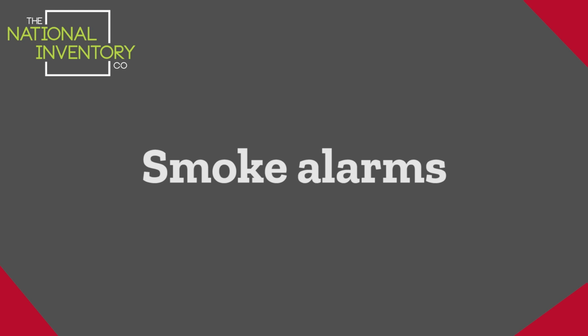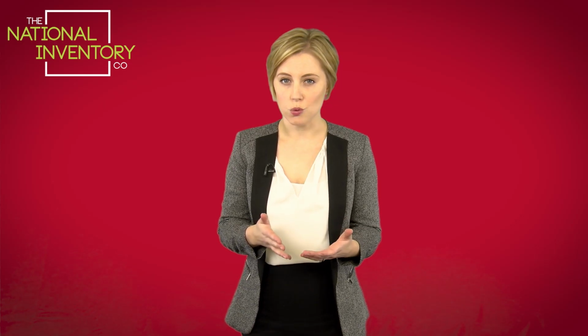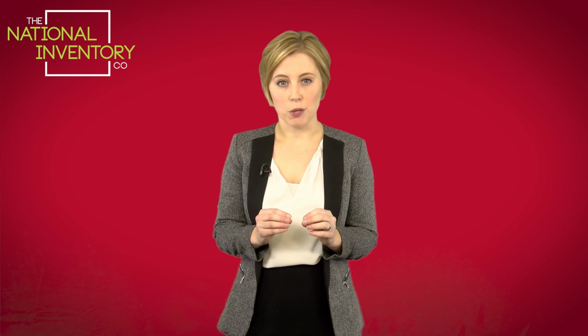Smoke alarms. There are a variety of smoke alarms on the market, mainly hardwired or battery operated. Hardwired smoke alarms are connected to the mains, but they also have a battery backup inside. In case the mains electricity fails, then the battery will kick in, allowing the smoke alarm to continue its normal function. When doing your fire risk assessment, you must ensure that the smoke alarm responds to push-button tests and also a smoke test.